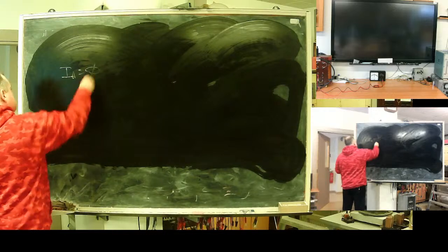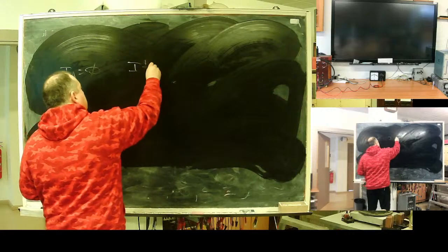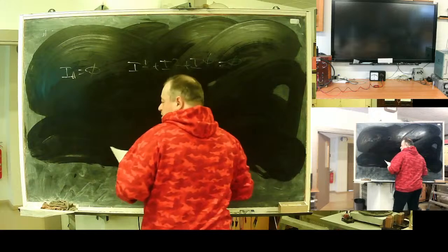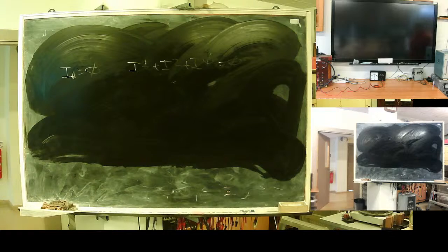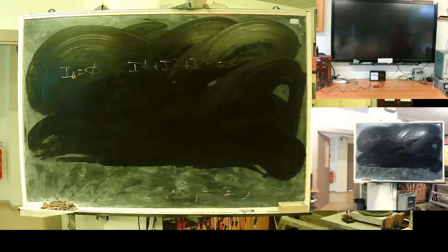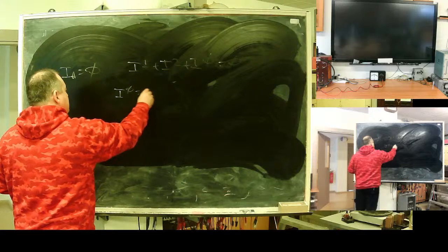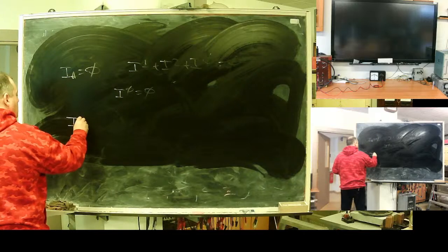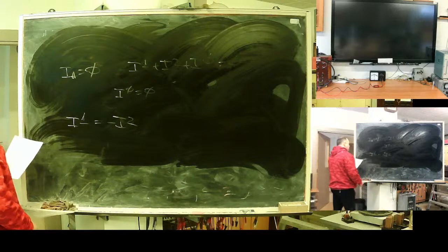The zero phase current is zero, and direct plus negative plus zero is zero because I don't have a ground connection. Earth fault protection should be immune to phase-to-phase faults. E0 is zero, no ground connection. So the direct sequence current equals minus the negative sequence current.